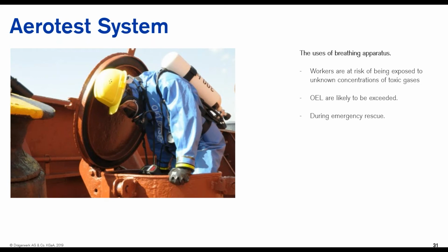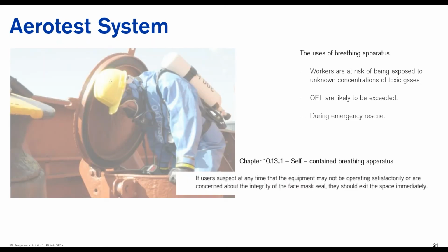So breathing apparatus that is being recharged in the vessels using the compressor might introduce contaminations. If you look into ISCOP chapter 10 under the self-contained breathing apparatus, if the users suspect at any time that the equipment may not be operating satisfactorily, they need to exit the space immediately. So when the users experience any odor or dizziness, this is where the contaminations in the air they breathe might be above certain limits. That's why they experience some discomfort.